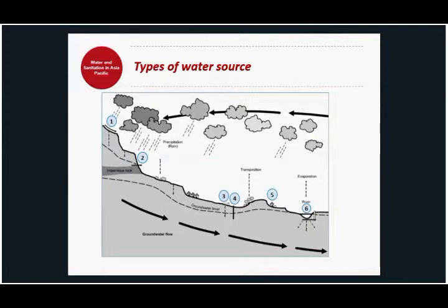Rivers and lakes are also fed from rain, surface runoff, and groundwater flows, and we can take water from those sources either directly or by making infiltration wells in the riverbank, which improves the quality of the water by filtering the open river water through the soil.